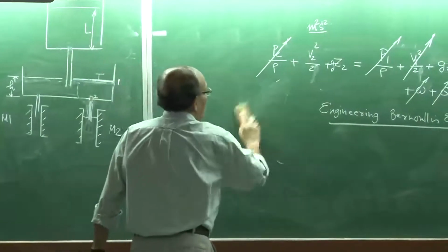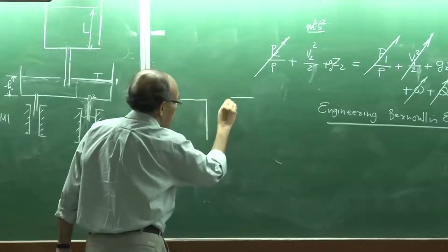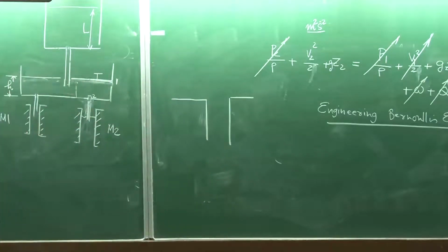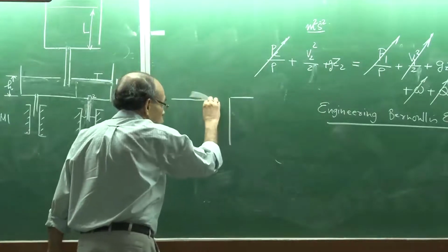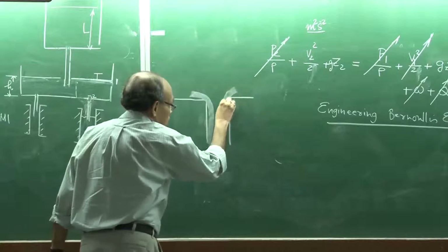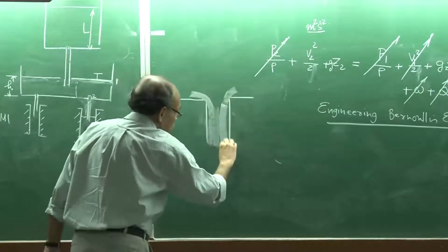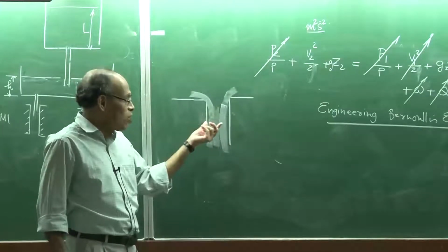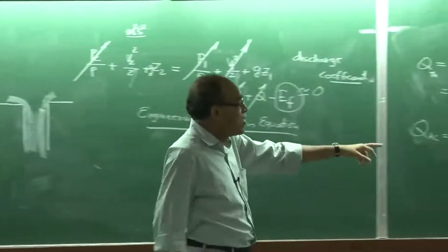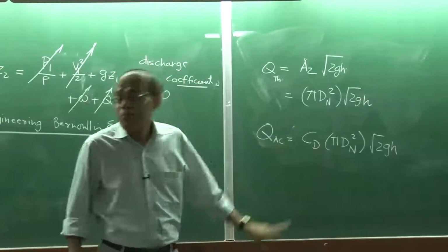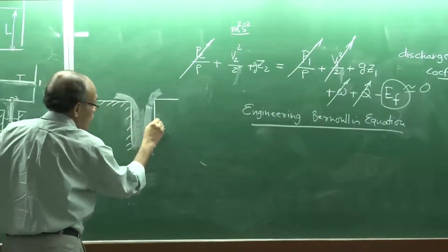Now, the physical significance of this is that when we have nozzles or orifices through which fluid flows, we can have various kinds of geometries. This is one kind. Actually when the flow really takes place, because of these sharp corners, the flow really occurs like this. So the fluid does not see the total cross-sectional area which is available. As a result, you can find that the discharge coefficient is going to be much lesser than unity for such sharp nozzles or sharp orifices.